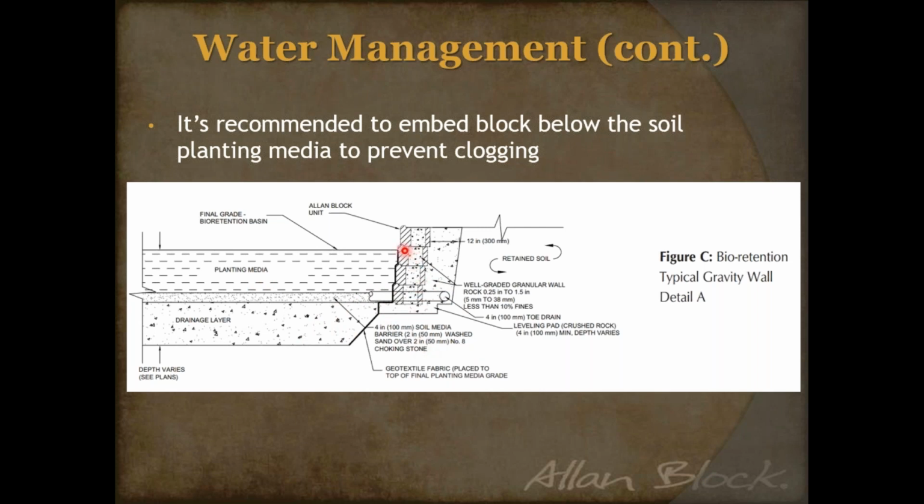I didn't point it out in the last detail, but in that last detail we still had embankment protection fabric in front here. That fabric is not impermeable. That fabric still allows the water to come in and out. It is really meant to keep that soil in place. So it's more like embankment protection, which is how I keep referring to it because that's what we see. But I've seen some engineers call it filter fabric, and that's what they qualify it as as well.